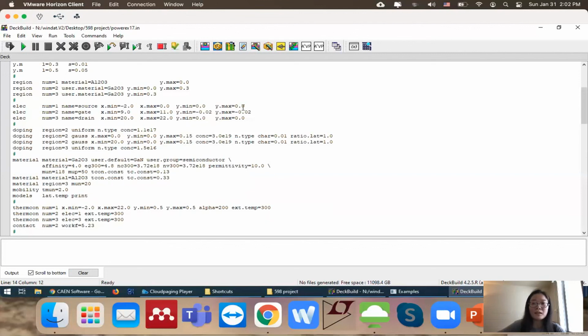You might wonder how come our two coordinates here are equal to each other. That means that our source electrode doesn't have any thickness, right? It only has the x coordinate and y is 0. That means it's like a line without thickness, and it is allowed in Silvaco.